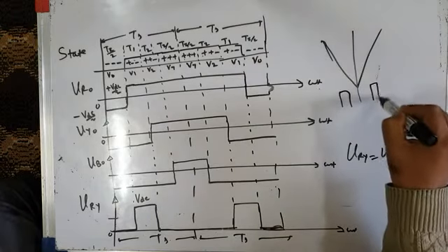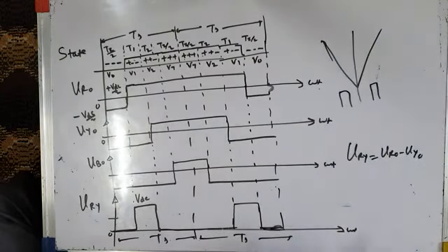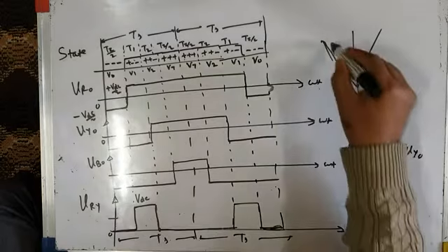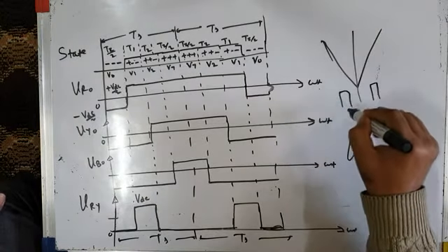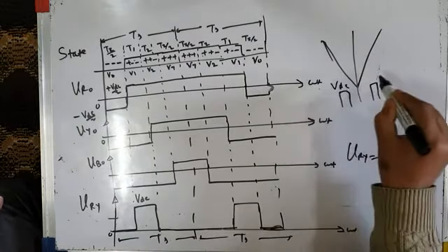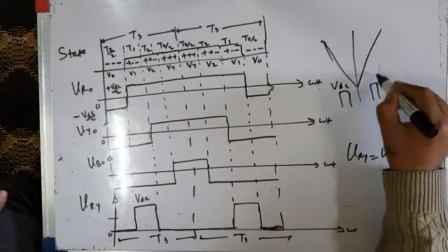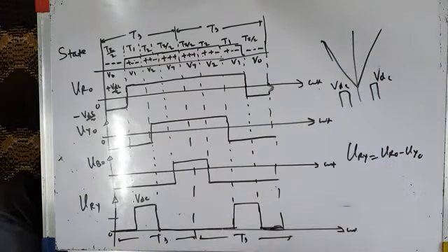In another sub cycle, another half carrier period, you have seen in triangle comparison also, in one carrier period, one positive voltage pulse will get applied across the load, VDC pulse. In another half carrier period, VDC will again get applied across the load.